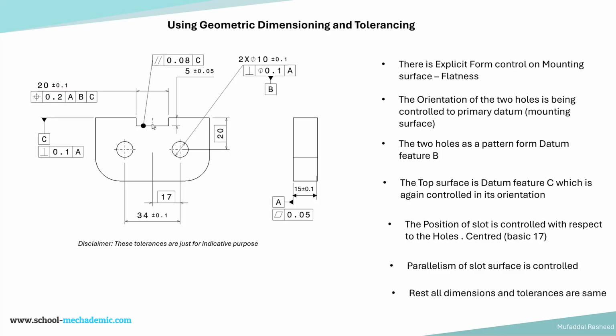We are controlling the center plane of the slot with respect to the holes, wherever the holes might be, because the main functional feature is the holes, because they are used for mounting. And so the slot has to be centered based on that. And parallelism is also applied, and all the rest of the dimensions and tolerances are the same.